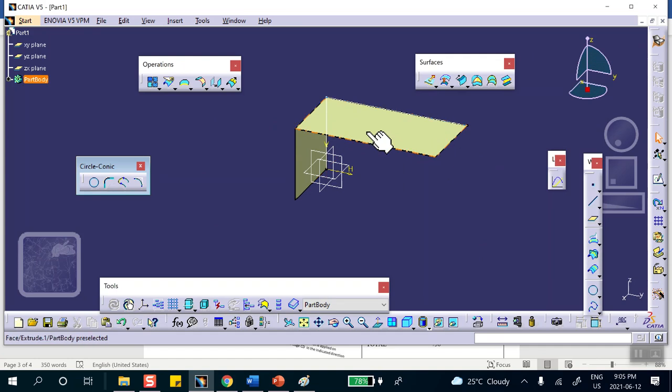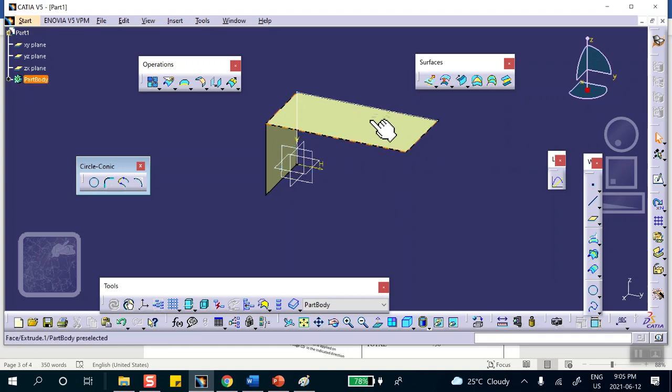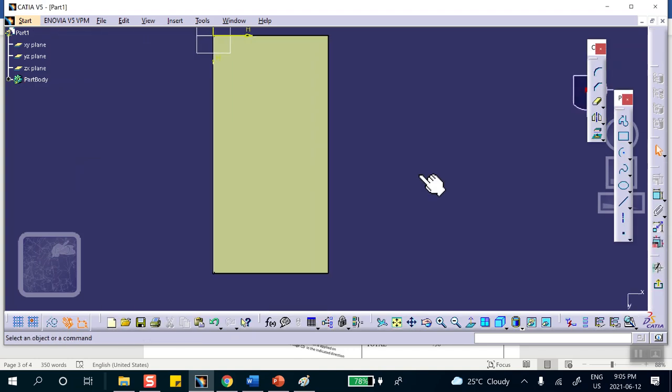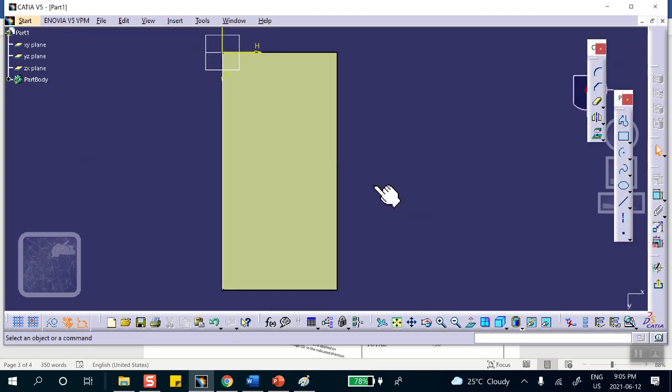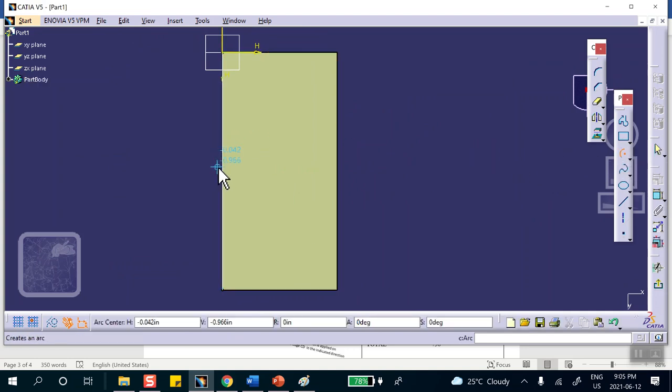All I need to do is to make some holes up here, one for the half a circle there, and also 1/4 of a circle at the bottom there. So on that plane, I will sketch. Now, let me draw that circle there. It really doesn't matter which side you draw it on.